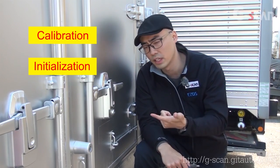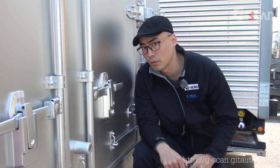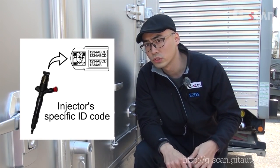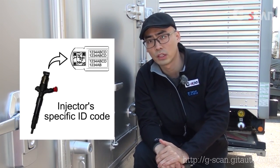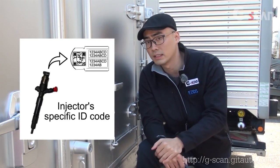Other than erasing and learning function, there's calibration, initialization, reset, and coding functions. One out of many different examples would be injectors. When you replace injectors, you have to code or write specific injector's ID code into ECU for correct fuel quantity adjustment. Let's see some special functions of Mitsubishi Fuso commercial trucks.